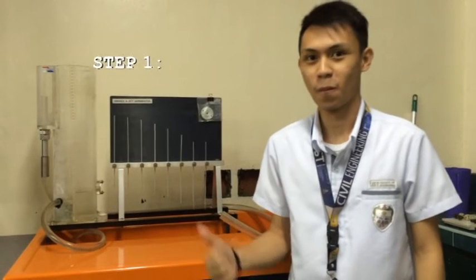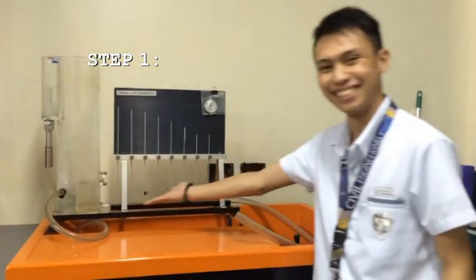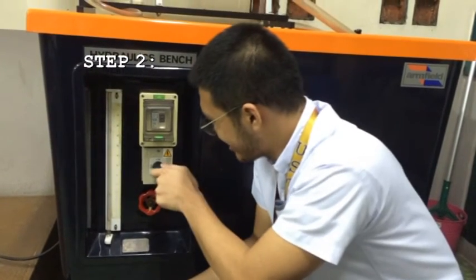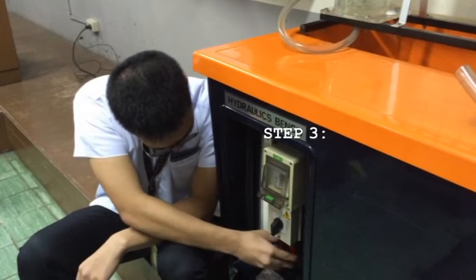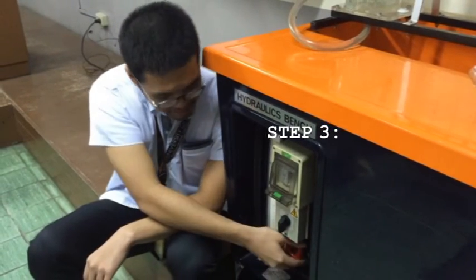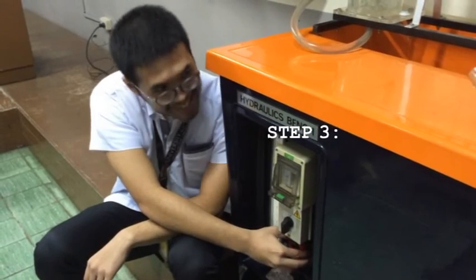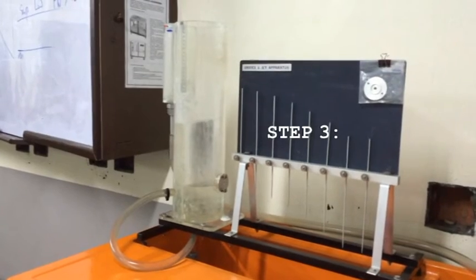Set up the orifice tank. After setting up, we now start the pump. Regulate the flow rate by means of the delivery valve to maintain the water level at maximum height. Care should be taken to ensure that this level is steady.